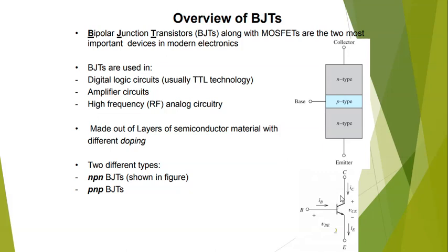So in circuit diagrams, when you want to show a transistor, we always use this shape. Base is always here in the middle. Collector is on the top. Emitter is here in the bottom, and the arrow is always with the emitter, right? So this is an NPN. When we have PNP, the arrow will be right here on the top, not on the bottom.